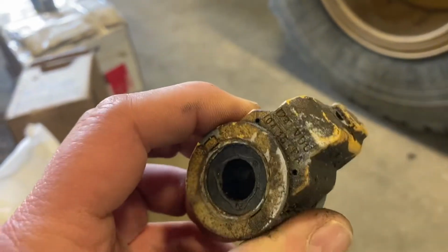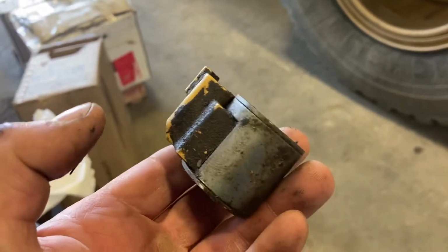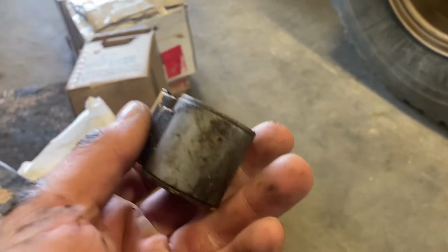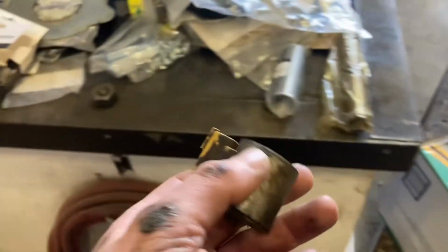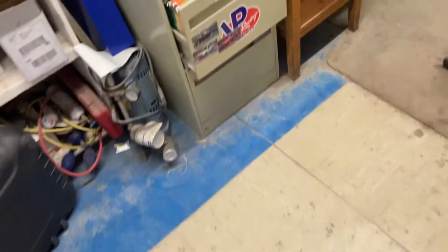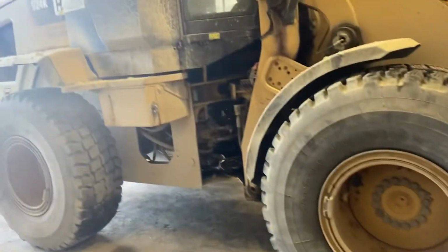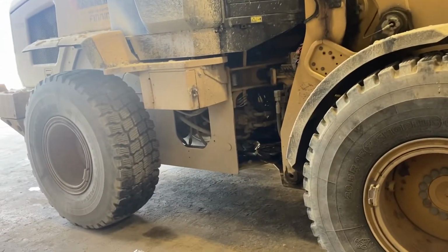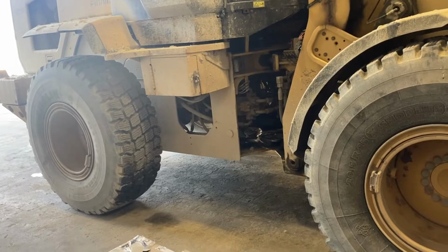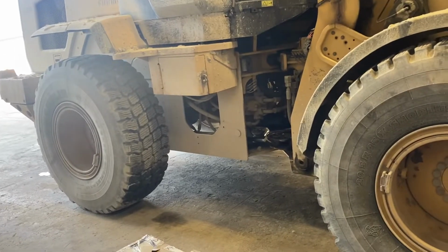What I found is the solenoid will be really hot when it starts to fail. And I'm not saying you just change it as soon as it gets hot. They get hot under operation normally, but I mean, you touch this thing, it's gonna burn your hand. And I've had that a couple times with solenoid valves, not just on this machine, but on another machine for a park brake solenoid. And like I say, you gotta check your resistance across the valve.